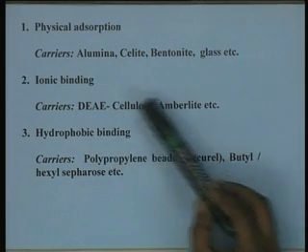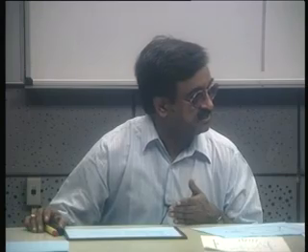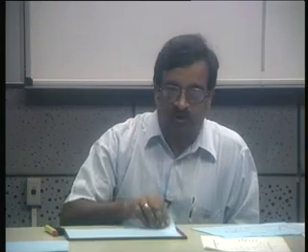For example, all the carriers for hydrophobic binding or ionic binding were originally developed for chromatographic separations, where the function is the same. That means you are binding through ion exchange interactions, through ionic interactions, and desorbing under conditions of desorption. So the same thing applies here. In fact, the preparation of immobilized enzyme by adsorption is very similar to chromatographic separations on ion exchange reagents, although we are only interested in the adsorption part, not desorption, whereas in chromatography both parts are of importance.